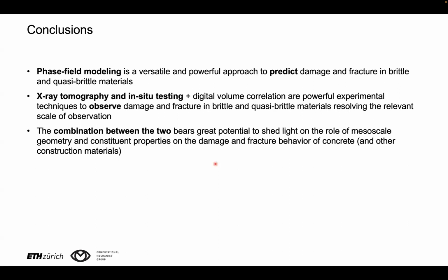On the other hand, we also believe that X-ray tomography with in situ testing has a great potential to observe in detail damage and fracture in brittle and quasi-brittle materials, resolving the relevant scale or scales of observation. And we believe that the combination between the two bears huge potential to shed light on the role of mesoscale geometry and constituent properties of concrete on its damage and fracture behavior. But a similar reasoning may be applied to other construction materials.